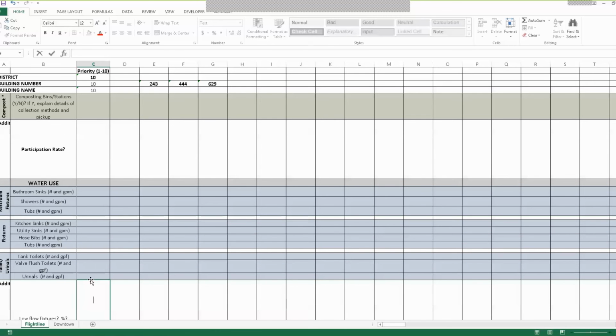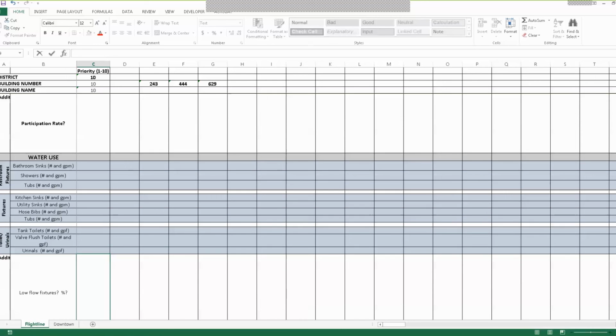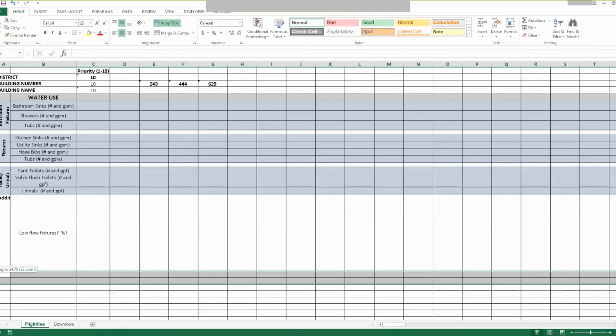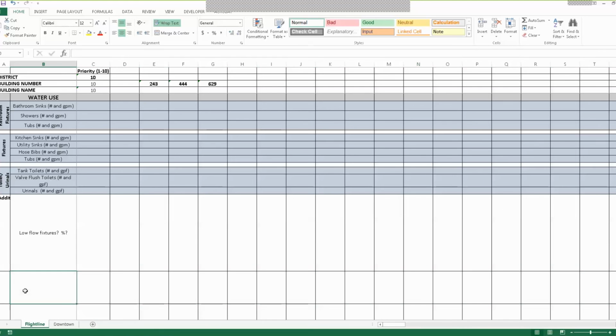We want to see if we can locate those, so that we can explain what that gap is, because we don't want to say it's all your system's leaking 50%. Could be, right? It could be that bad. But we want to get an idea about what all those additional large water users are outside of the building.